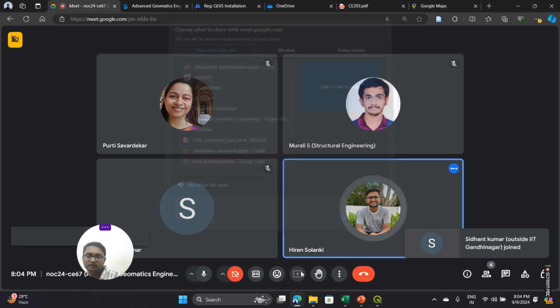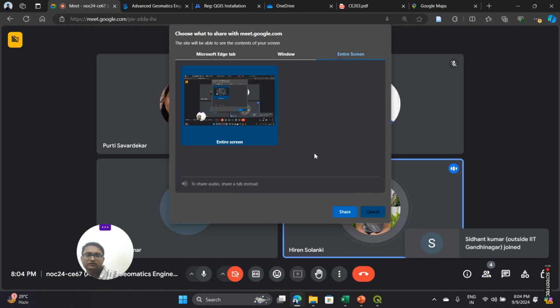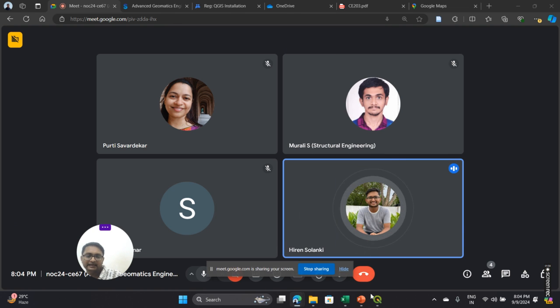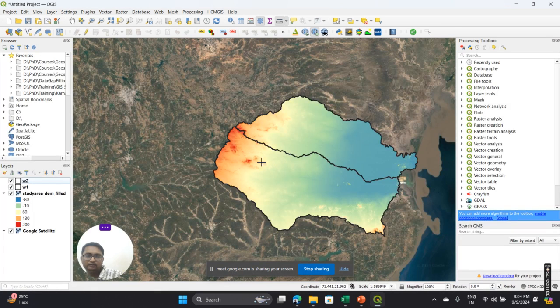So see, there are different visualizations in QGIS. Here it is continuous in nature. So blue color is given to -80, this green color is given to -10, and whatever value comes in between, it will interpolate for the in-between values.